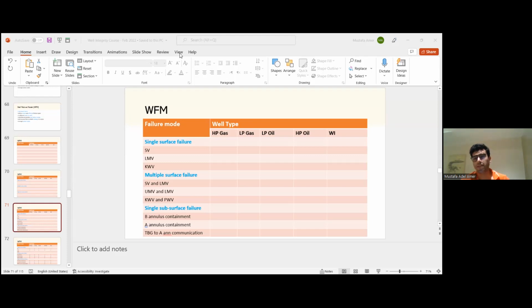Can't tell. Producing brine. Maybe you have an active surface formation water, and you don't have good cement in the B annulus. It depends as well where the B annulus is connected to the formations and the mud log. Is it cemented behind it? You trust the cement, or you don't trust the cement.